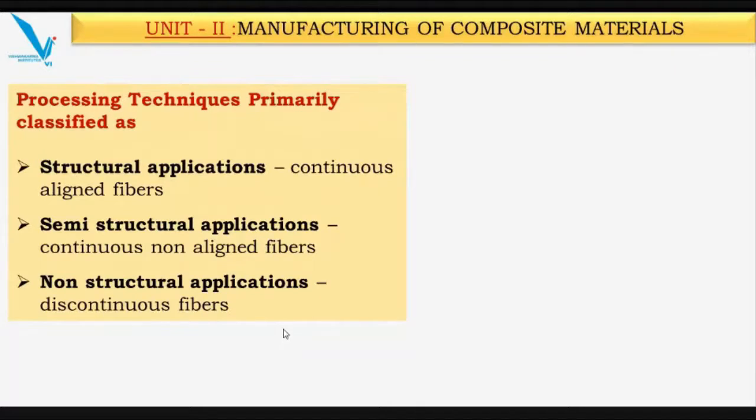You cannot compromise anything, because that particular composite material is directly subjected to various loads; they are load bearing applications. Then there are semi-structural applications, also in marine applications and some construction applications. There also we have to select the proper manufacturing techniques. And for non-structural applications, hand layup and spray layup generally come under them. So based on the application and loading conditions, these manufacturing processes have been classified.